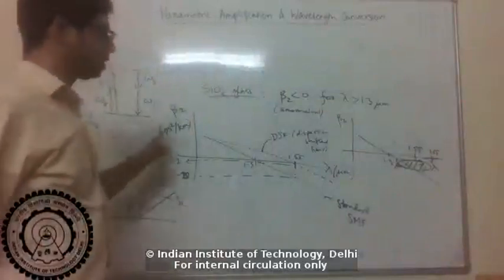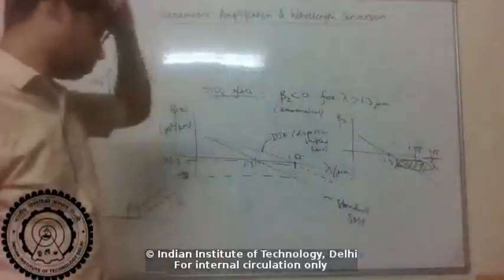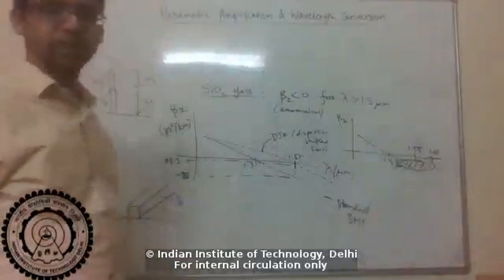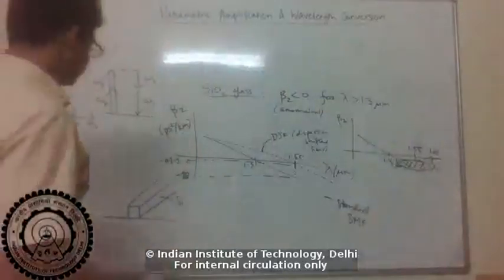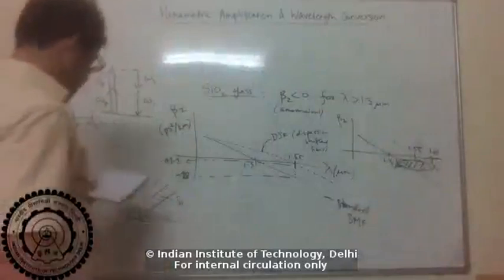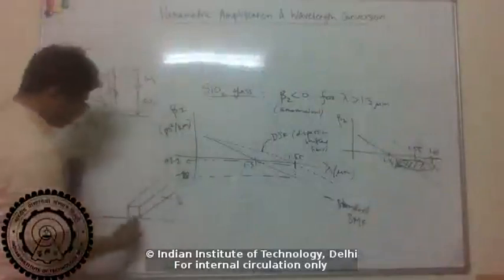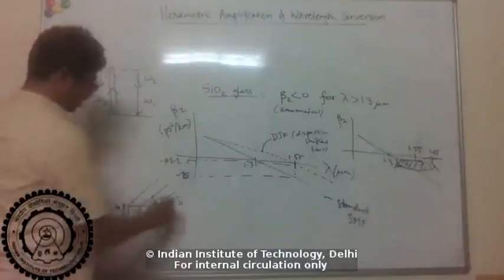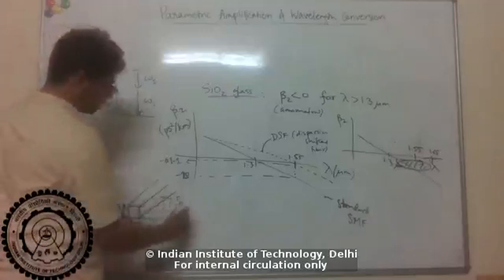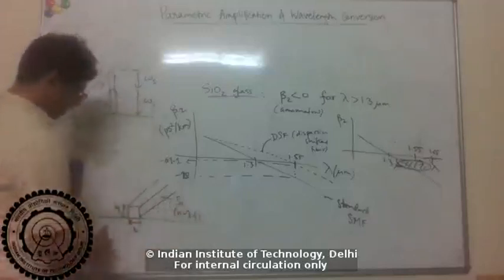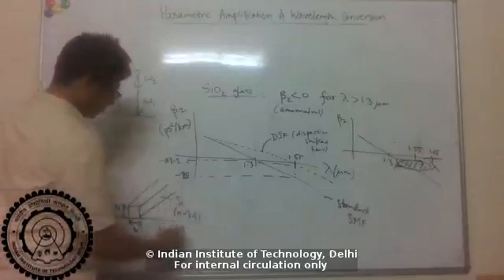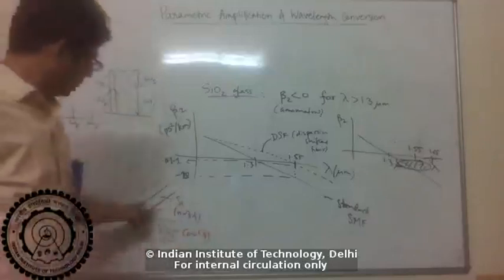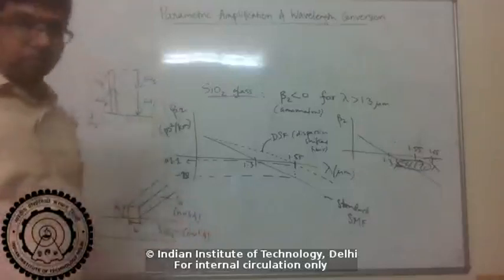But there was this whole push of doing nonlinear photonics and a lot of this telecom stuff, shifting from long fibers into small on-chip devices using silicon. Right. So then, how do you do that? Here, what is done is that the waveguides can be made very small. The dimensions like the width and height, because the refractive index of silicon is so large, about 3.4, right? And typically this will sit on some substrate of glass, which has refractive index 1.4. So the index contrast between the core and cladding is very large.